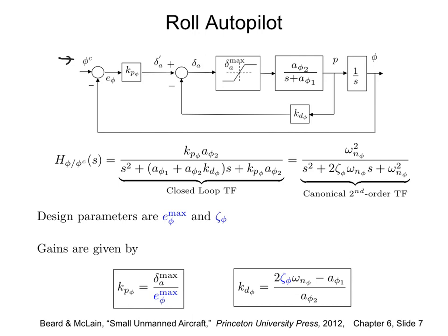So the idea is again same, we are using a Kp Kd controller here, so PD controller, and this is the transfer function that we got from there. A phi 2 and A phi 1 are the coefficients, and when we apply that, we get this closed loop transfer function here. Okay, so this is the ratio of phi commanded over phi, or transfer function of phi commanded over phi.